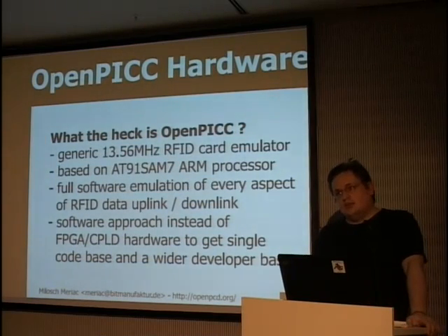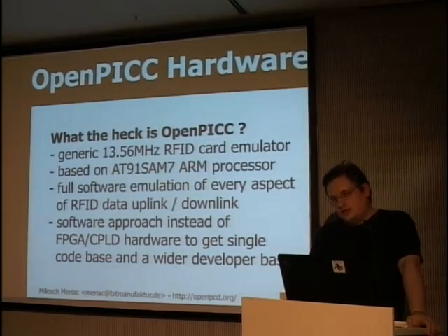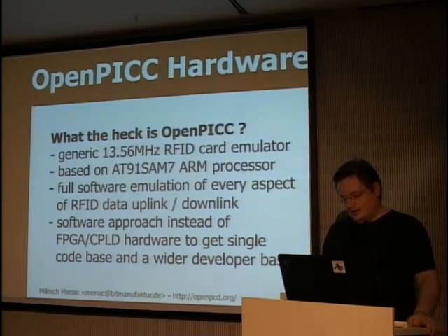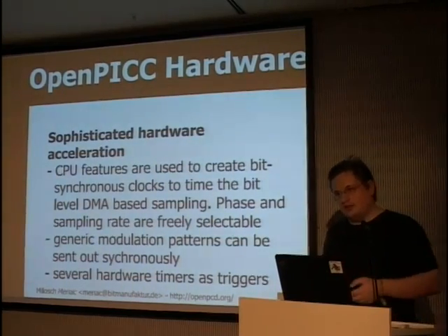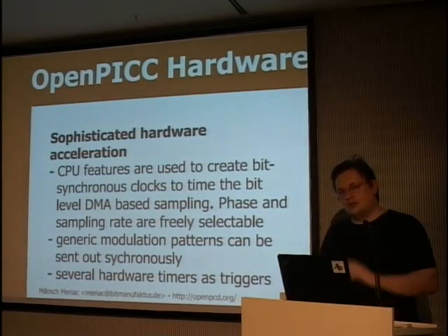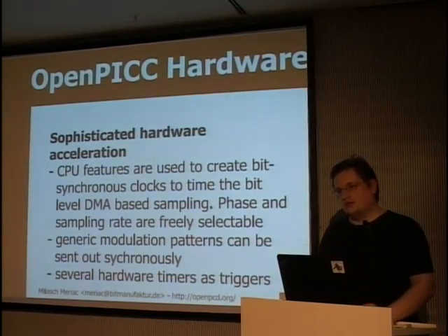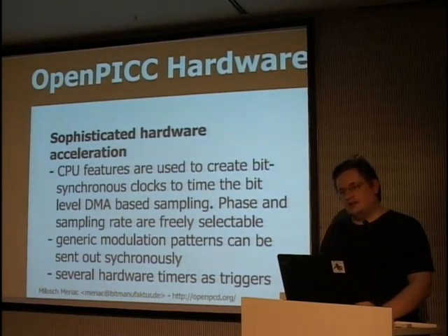So to be able to do this with as inexpensive a CPU as possible, we carefully chose the device. And if you have a look at the schematics, you find that we very heavily use the hardware acceleration features that it provides, not only the timers, there are several timers used. We, for example, use functions that are used for telephony protocols to act like trigger conditions on data.